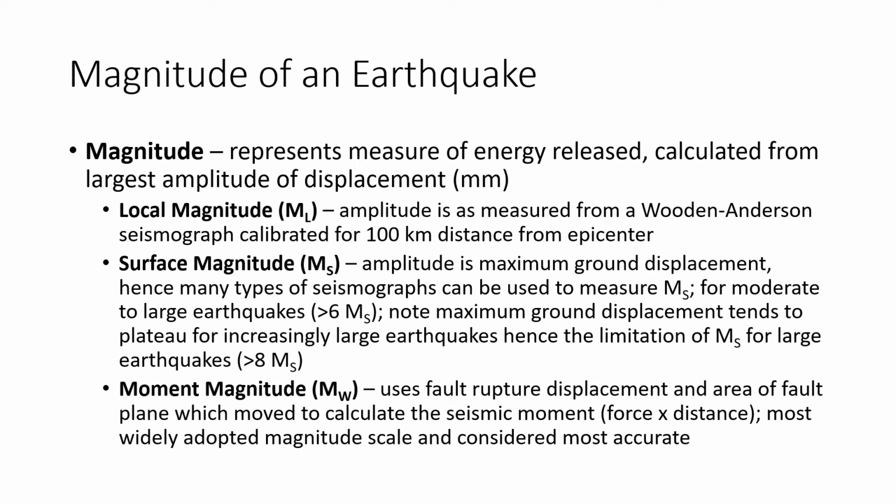It means that after magnitude 8, the value of maximum ground displacement tends to plateau. So it flattens to a certain value. So an earthquake bigger than 8 might not necessarily have a much bigger ground displacement compared to a magnitude 8 earthquake.